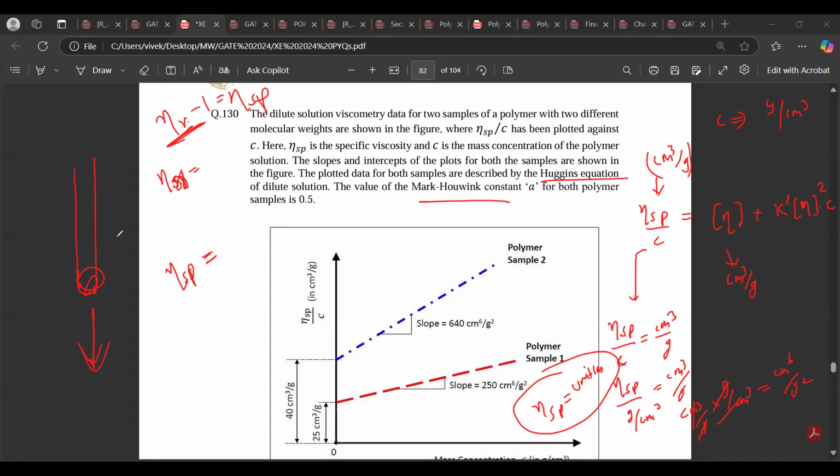This is a typical test that we do to find out relative viscosity. All these quantities should be tested in the experiment in your lab, then it's very easy to memorize. So eta relative is how much time the solution took, because if it is very thick, with very high viscosity, it will take a very large time, right? So how much time the solution takes divided by the solvent, which is a liquid like water that will quickly come down, right? How much time the solvent is taking. So usually it's greater than 1, unless you're mixing something with the solvent that makes it even thinner, which is usually not possible. And then eta relative minus 1.